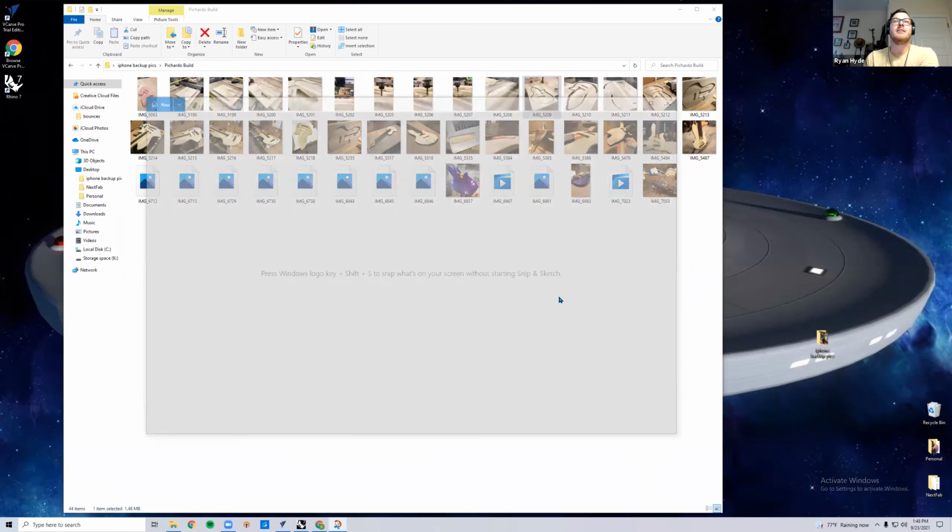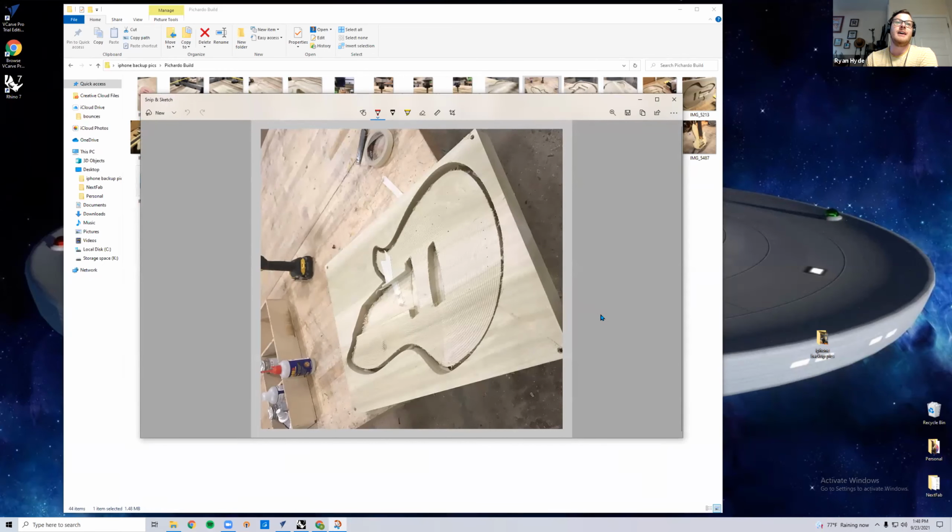So after that, you're going to do what's called flip machining. And a lot of people ask, what is the crazy thing about two-sided machining? And my answer is that two-sided machining is just doing one-sided machining twice. But the key is the registration. So that's why I sort of built a pocket for this block of wood to fit into exactly, so that I can just re-register it at will.